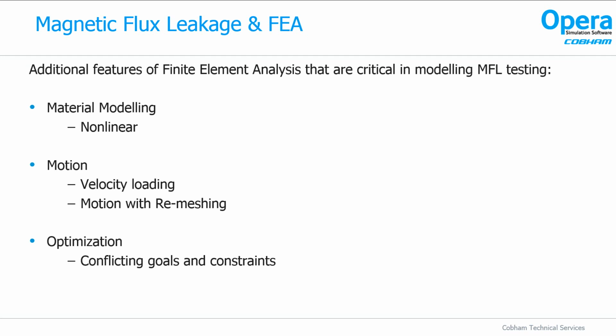Let's now take a look at some features of finite element analysis which are crucial in successful, efficient use for solving MFL simulations. Because the method relies on inducing a high magnetic flux density in the pipe, accurate nonlinear material modelling is a must. High-speed, non-destructive inspection systems using the MFL method are in great demand for online inspection and defect characterization, especially in pipeline maintenance. Such schemes aim to deduce the shape and dimensions of a flaw from the voltage induced in a pickup coil, moving relatively quickly along the structure.